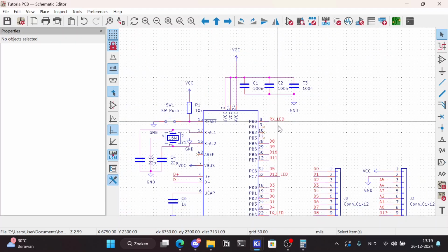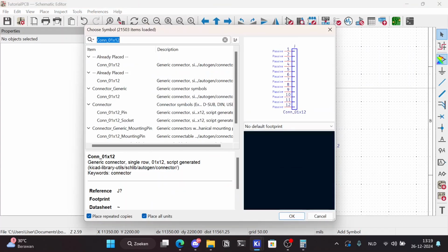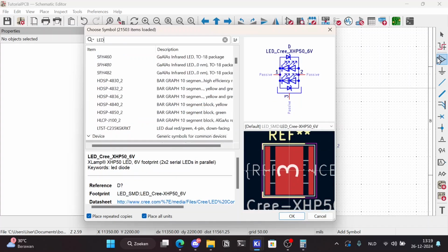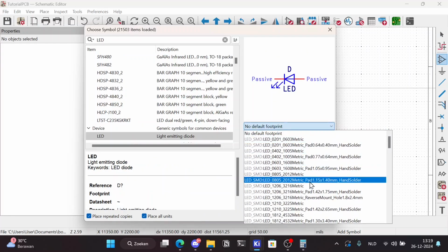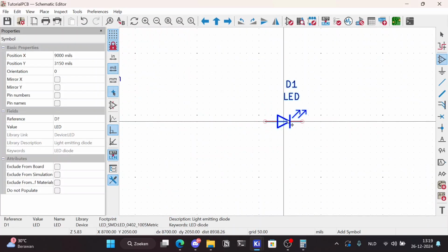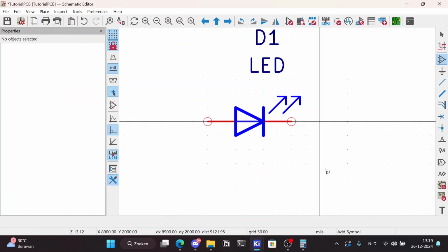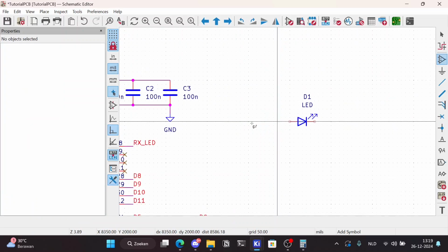Now we'll route the LEDs. So for that, you need to make at least a kit, or that's what I call it. So you go into here, LED, no default footprint. We'll use 0402s as usual, and you can use this diode polarity. So that means this will be ground, and this will be the positive terminal.